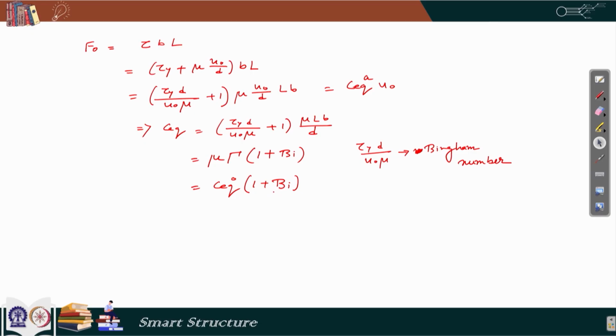So, these are the two cases that we have described so far. One is the flow mode, another is the shear mode, and under each of these modes we have non-zero applied field and zero applied field. We have seen that in flow mode several regions come out because of the non-zero applied field. In shear mode we do not have that. Shear mode is somewhat more simplified in terms of analysis.